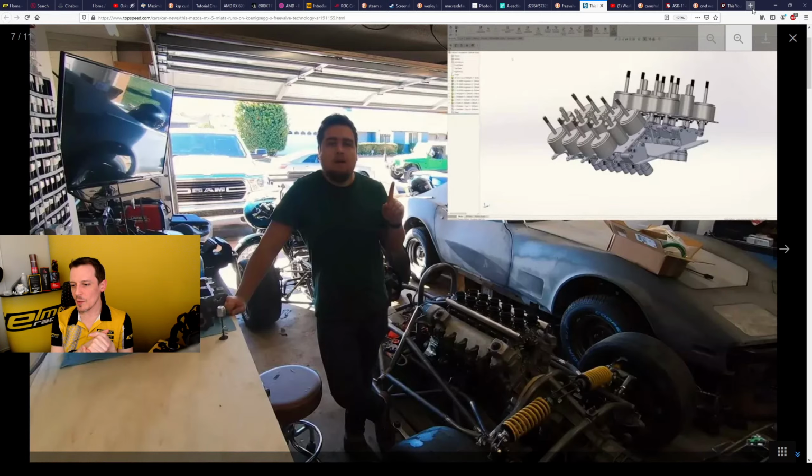Band sits directly on the top of the valve, no rocker in between. Yeah, I have seen that. So the Koenigsegg system does not use any rocker type things, which is definitely a potential benefit. There are also other benefits that Koenigsegg is planning on using, like having 2 exhaust valves, where one exhaust valve goes to the turbocharger, and the other goes into the exhaust system directly, bypassing the turbo. So then you can run at different load conditions. You can vary the lift depending on how much turbocharger you need or don't need, which is potentially very beneficial.